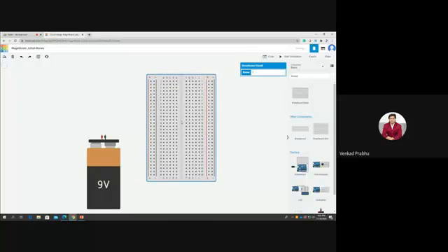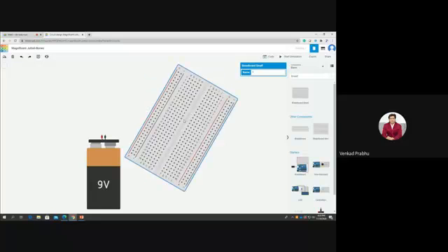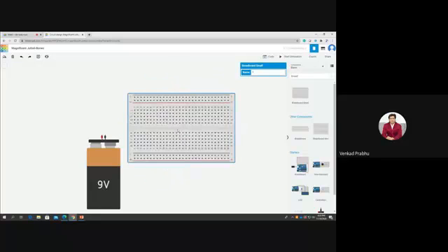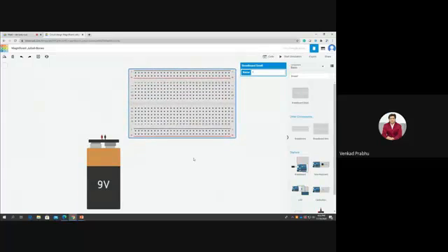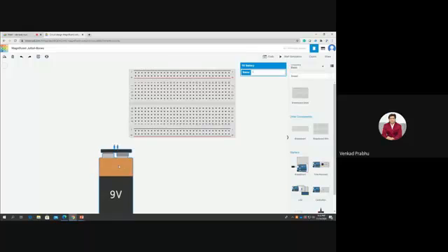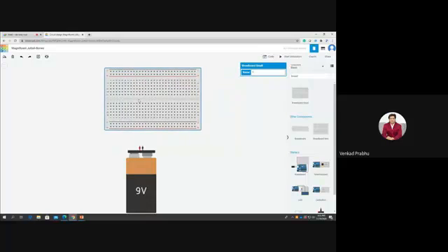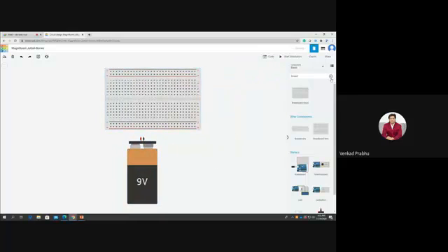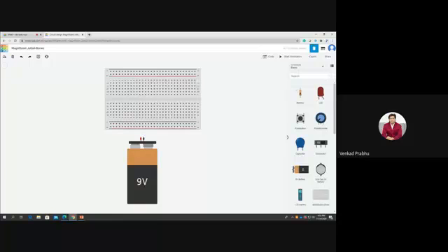So for better viewing, I'm going to place this breadboard like this, and Control scroll if you want to minimize it. Now I'm going to connect 3 LEDs, for example. Remove the search on the right hand side and choose the LED, and first I am going to fix it inside the breadboard. As I told before, if you go inside, each slat is going to act row wise.